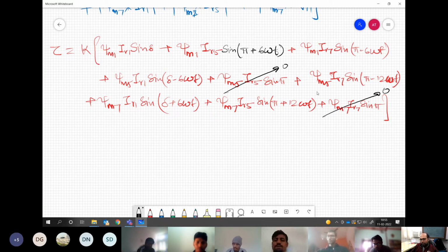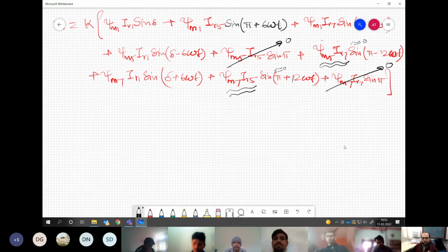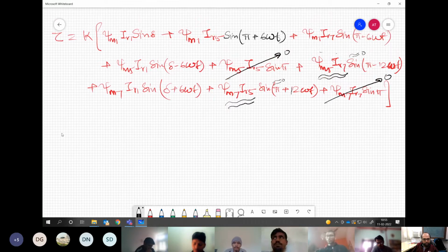Then you have product of two harmonic quantities over here at two places generating some component. Because this is product between two harmonic quantities, we can take this nearly 0 compared to any other quantity where you have fundamental and one harmonic. So obviously the amplitude is more. Here the amplitude is very small. Harmonic into harmonic, correct? So this we can ignore comfortably compared to any other component over here. Now we are remaining with only 4 components in this expression, or 5 components rather.